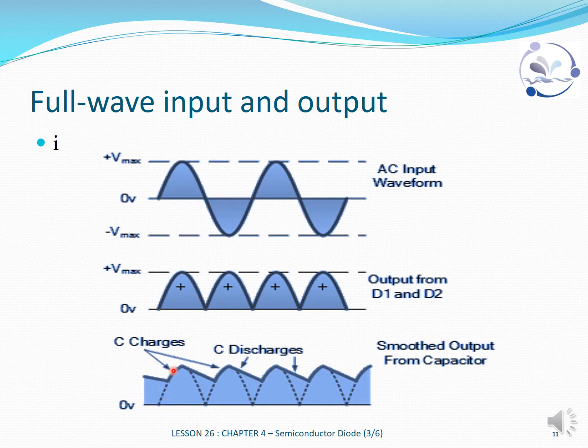So we have our capacitor charging, discharging, charging, and discharging. And because this is the full wave, we must remember that our discharging time is quite small compared to that of the half wave.